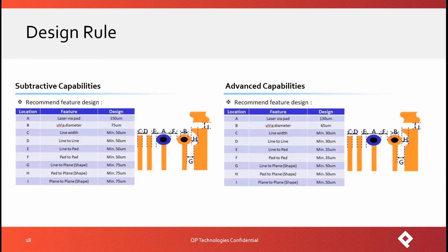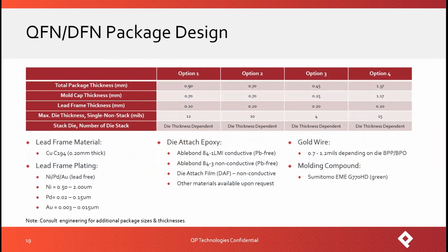and other details. Typically, with the thrust into tight pitch flip chip, meaning 150 micron and below, you really are stuck having to pay the bucks and wait the time to go to the 30 micron or thereabout line and space. ABF or some other variation. Everybody's trying to get into that business now, but historically, we only had two North American vendors that we worked with that had the capability to do the advanced work. There are several that are emerging, and most of the time we actually had to rely on a partner in the Far East for that.